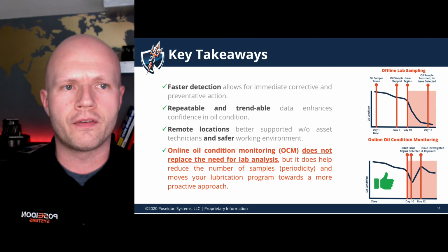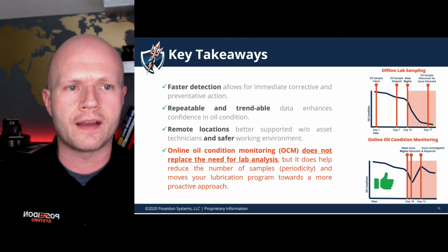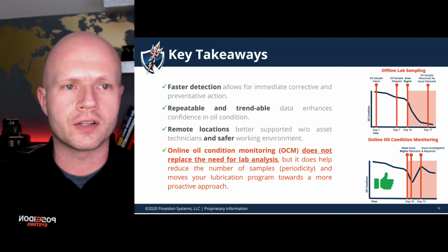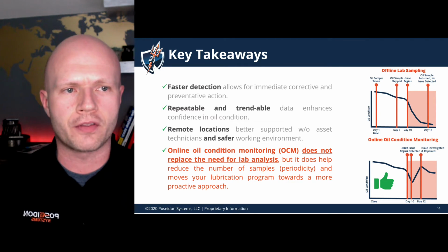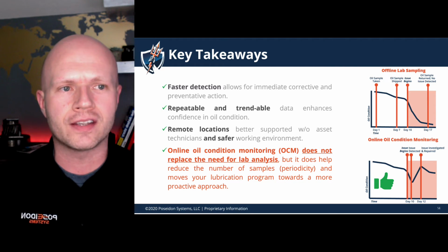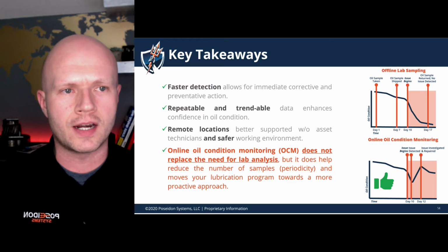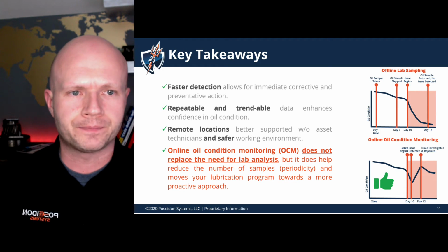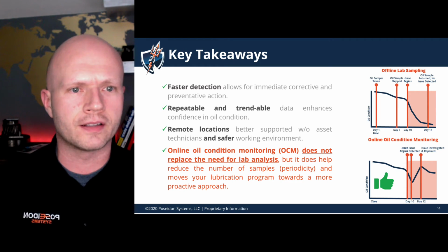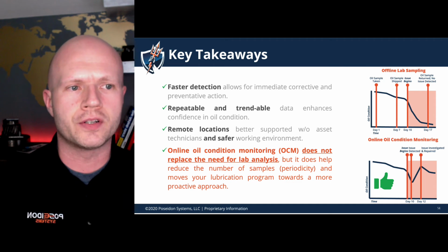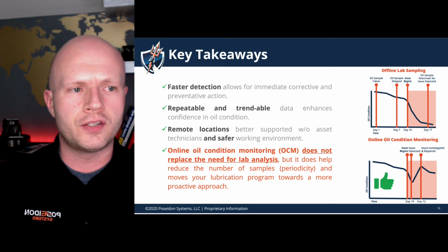For those of you who have very remote locations where you do not have technicians there often, you can save a lot of cost of having and forcing them to go there to take those oil samples or do some other things. But if you do have the technicians on site, just not having to get them into that working environment as often while pieces of equipment may or may not be in operation or running is a big safety improvement. But we do want to make sure that we're very clear that it is definitely not a complete replacement for lab analysis. Definitely will help reduce the number of samples, but they do go hand in hand.